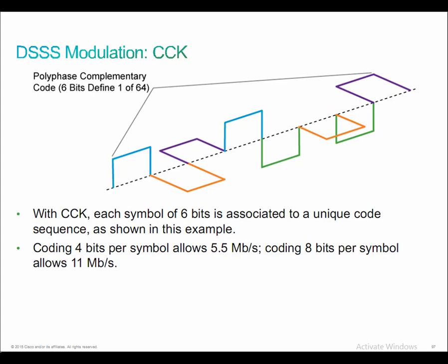So we can't really make the signal go any faster by keeping the Barker 11 encoding scheme. We can't shift more than 90 degrees, obviously. If we went to an 8 shifting technique instead of a 4 shifting technique, you might miss one of those shifts within that short time period, and the data might not be represented. All right, so to increase the speed in modern DSSS modulation techniques, we use CCK.